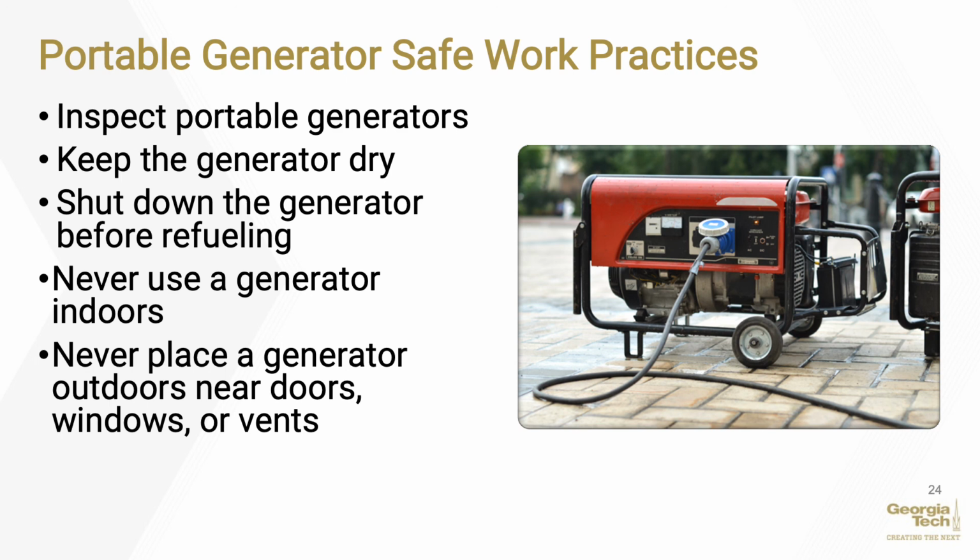Never place a generator outdoors near windows, doors, or vents. If you or others show symptoms of CO poisoning, dizziness, headaches, nausea, tiredness, get to fresh air immediately and seek medical attention.